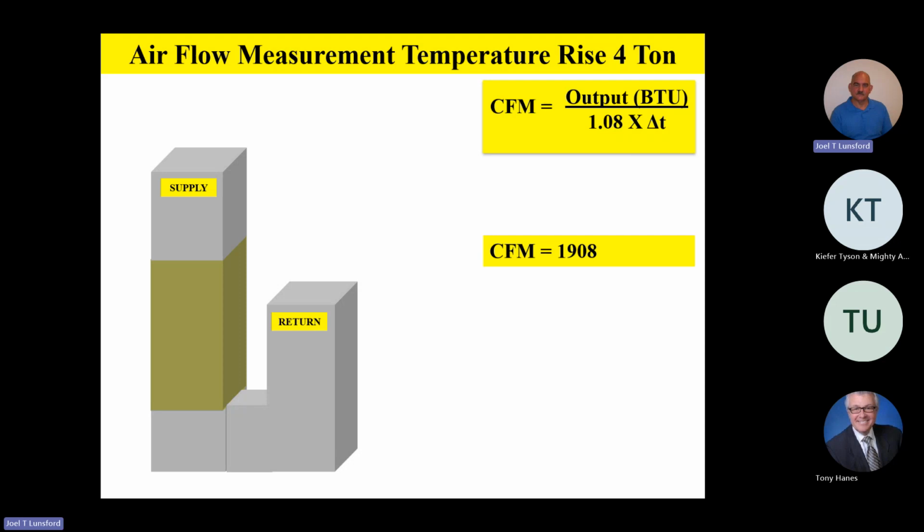So this works in the wintertime. It works fine in the summertime. Just remember, if you're doing it in the summertime, you don't want to put too much heat into the house, obviously, but this is a quick, easy way to confirm airflow. And I've used this method for over 40 years as a technician, and actually I've been in this industry almost 50 years now. Next spring will be 50 years since I graduated technical school, and I learned this way back then. So this is a very old method of airflow measurement, but it works very, very well, especially on air handlers with a heat strip.